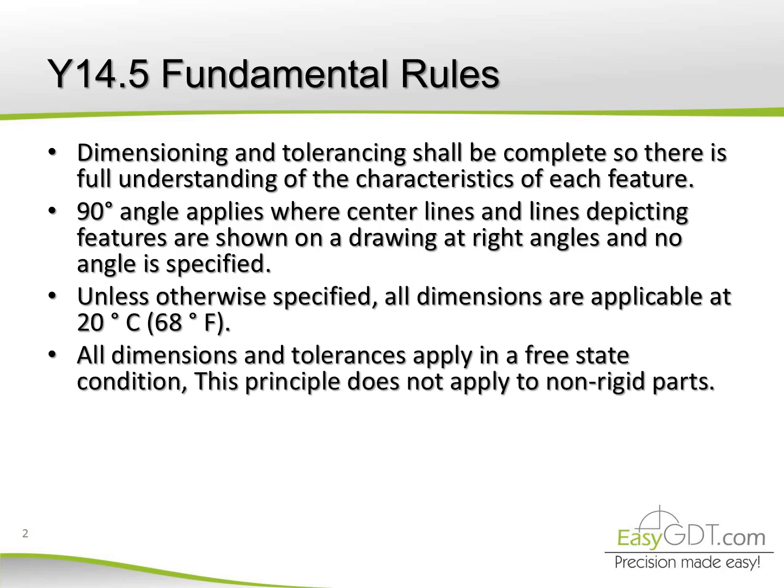All dimensions and tolerances apply in a free state condition. This principle does not apply to non-rigid parts, so the parts can be deformed to make them comply with dimensions.